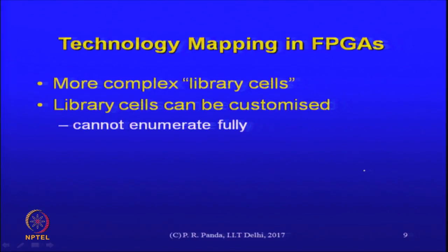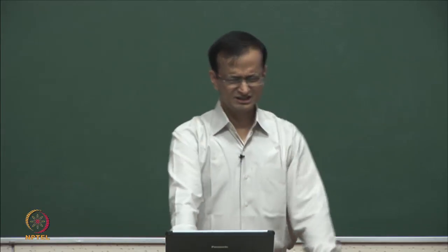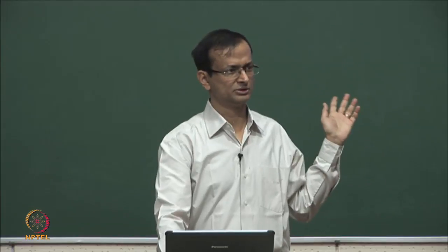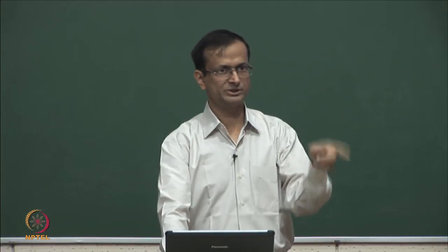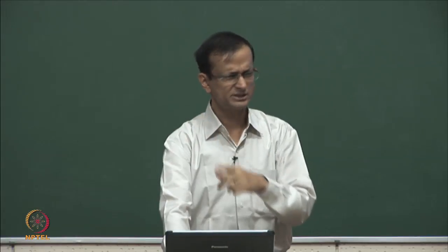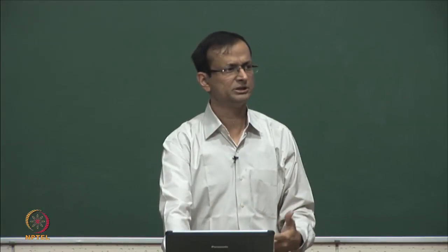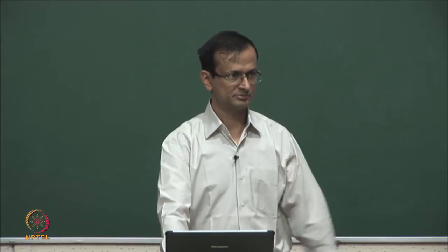With that kind of a logic structure, how would logic optimization work? First of all, we have 2 phases, right, in the multi-level logic minimization. There is nothing particularly 2-level about this. The whole point is that you can take the output from one of these CLBs and take it to a different CLB. It is in a very natural way amenable to multi-level logic implementation.